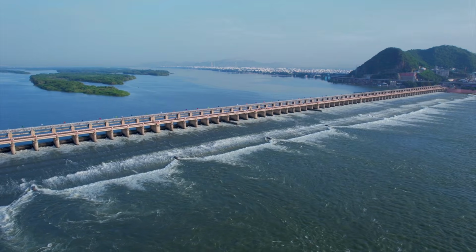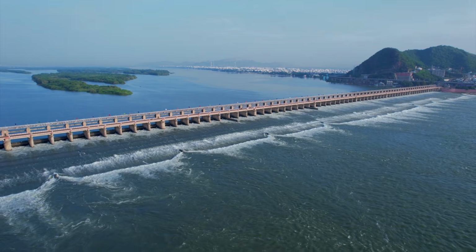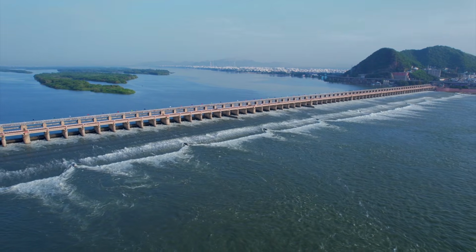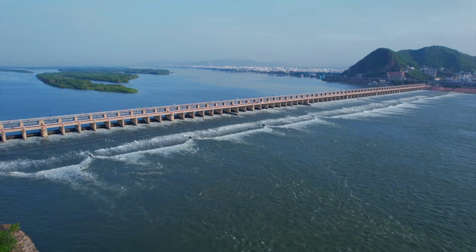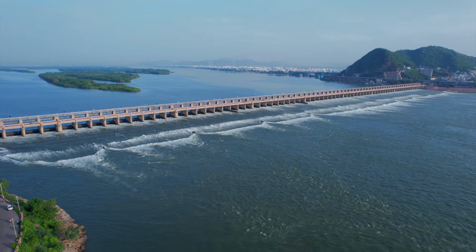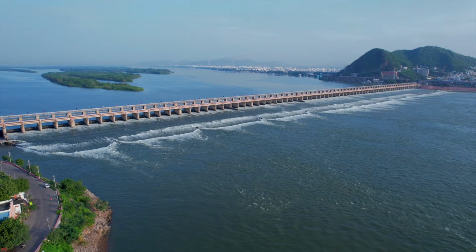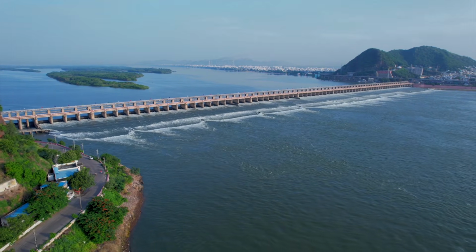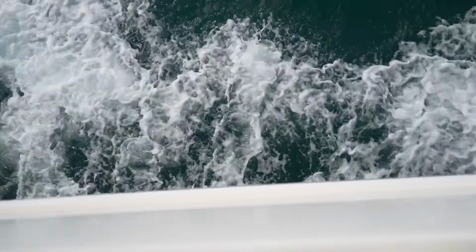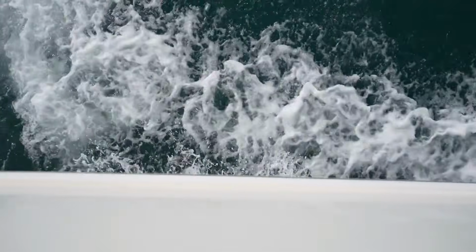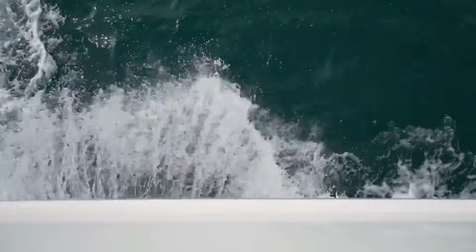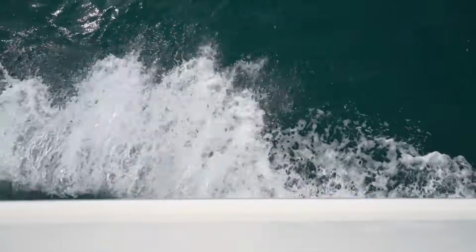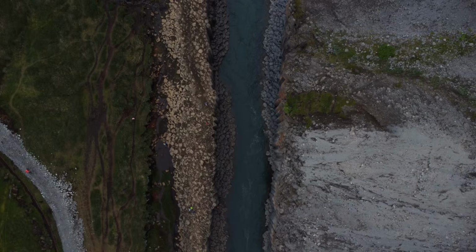From the rarefaction waves that travel backward into the reservoir, to the supercritical bores that roar through canyons at terrifying speeds, this video explores the fluid mechanics that make these events so destructive. We break down the Saint-Venant equations, the role of the Froude number in supercritical flow, and why a wet bed flood travels faster than a dry bed one.